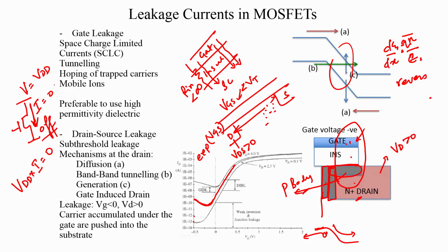But because you now have a leakage current, since I is not 0 and you have all these leakage mechanisms, you have static power consumption in a MOSFET circuit, and this power consumption exists even when all the MOSFETs are turned off, and this is going to drain the battery charge because it is going to continuously drain this much of power from the battery.